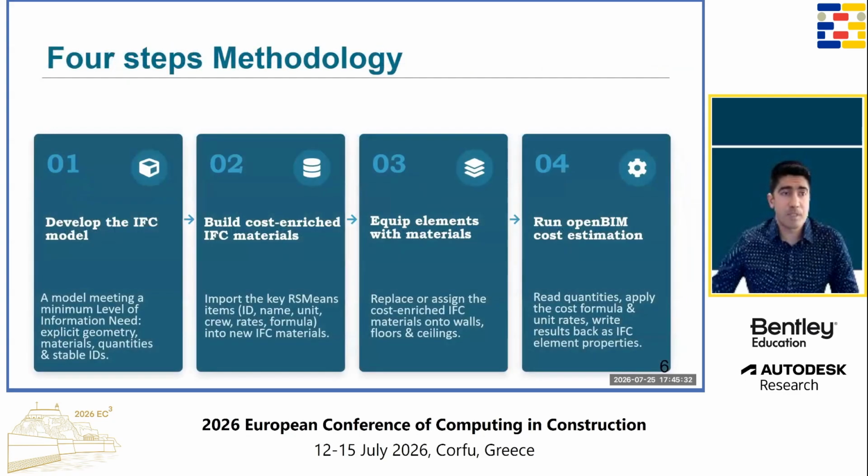So the four-step methodology includes developing the IFC model, building the cost-enriched IFC material, equipping the elements with those materials. So it means replacing or assigning cost-enriched IFC materials.